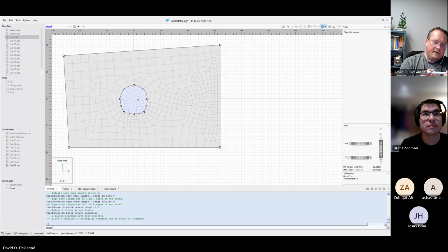If all of a sudden we jump too far ahead and we excavate not 3 meters of rock, but 30 meters of rock, that tunnel's probably not going to respond in a good way. And so numerically, what we do is we play around with things like the modulus of the material, and we can dial that down from being equal to the rock around it to a lower value. And then we're also constantly sucking energy out and controlling how these boundaries are behaving so that it all comes down to a nice convergence in a clean way numerically.